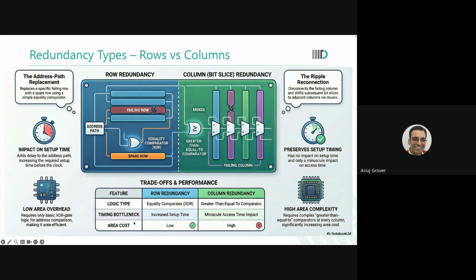See, suppose a contact did not come out well. At the first run itself, you know this memory set is failing, and I need to repair it. Now, suppose the contact did not come out well, but not very badly either. What will happen? All your tests will pass at PCB. All your tests. So, even though there is a weak memory cell, the tests will pass and you will be able to get a memory going. You can ship it to the customer.